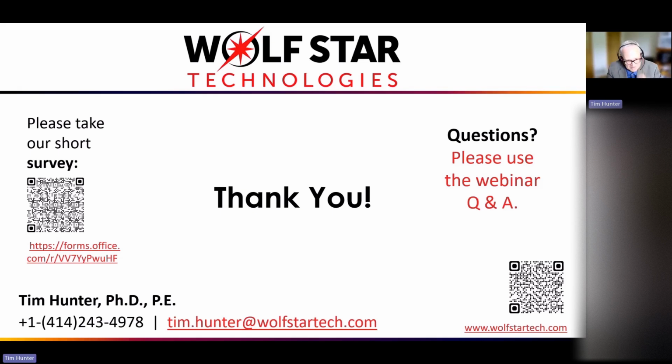Another question here is how do you handle dynamic and harmonic loading? Okay. A lot of people are working with structures that have harmonics present in them, and so what we do is we have our customers, rather than putting on static unit loads on their structures, solve their models for eigenmodes, and then they can choose the modes that they're interested in, and we'll lay strain gauges to sense those modes.